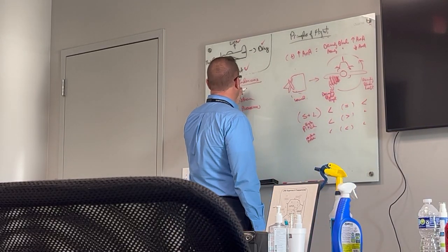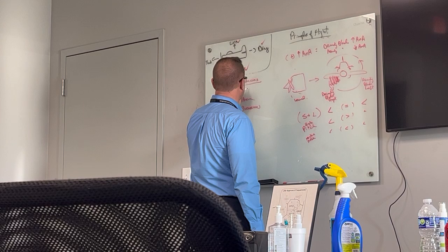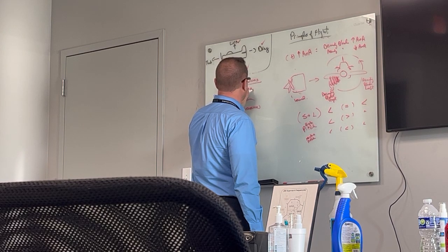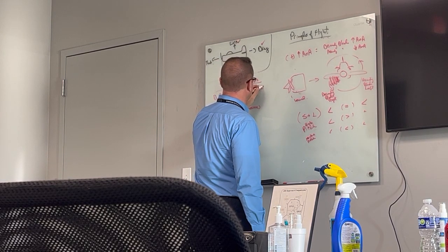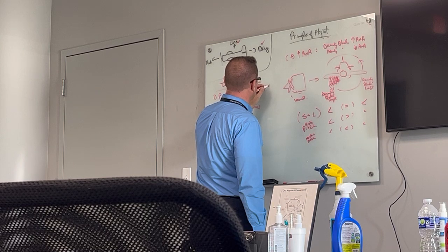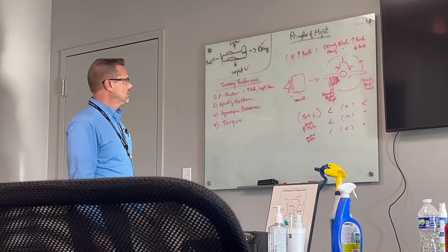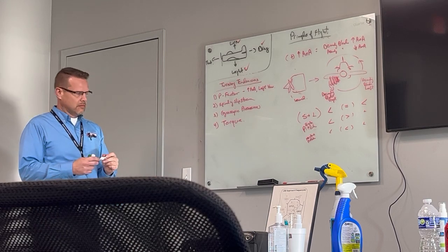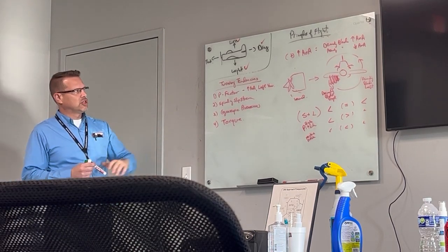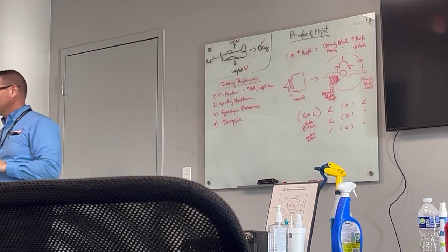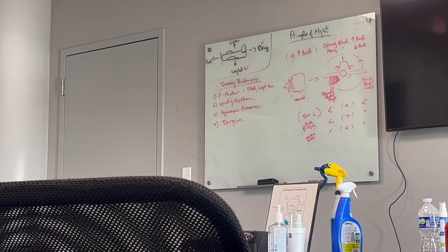So this will be at high angles of attack. It'll give us a left yawing tendency, or left turning tendency. And you can try and draw some of this stuff on the board. A lot of it, like I said, that little prop is worth its weight in gold, because you can just show that and go, look, when I tilt this up, look what happens, and that's it. And then you're good to go.